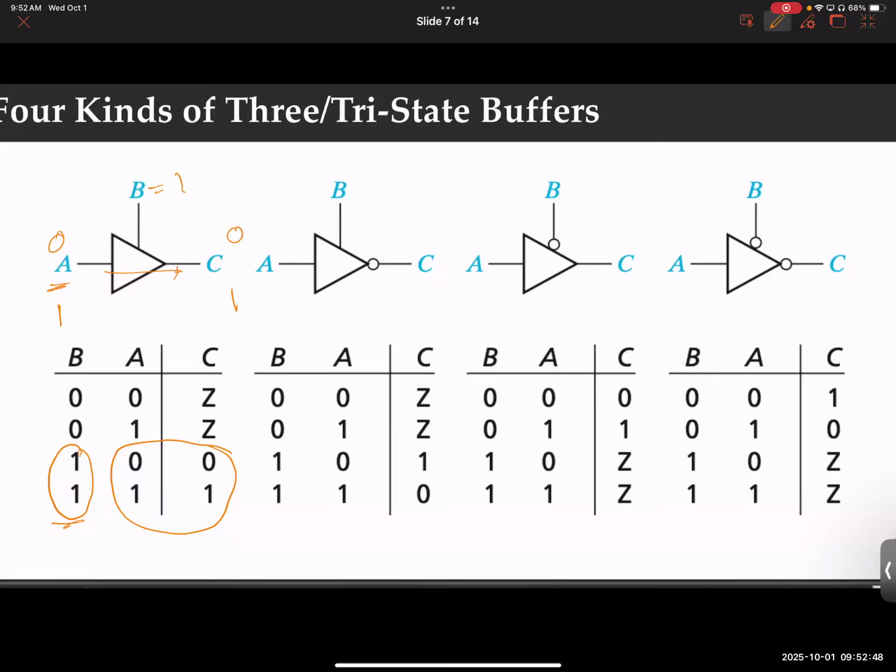This is exactly a use case for a gate like this, where you just let it float. Does that make sense, folks? And if you make it 0, it's not going to go up because you're driving it to 0. If you connect it to VDD, it's going to stay at VDD. It's not going to change. So to sense the stored data, how do I know what it's storing? That's how we read. You basically let it float.